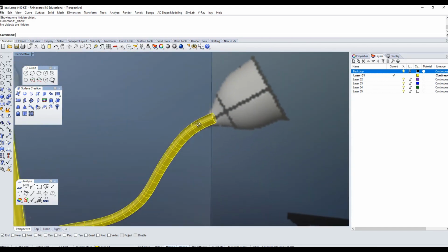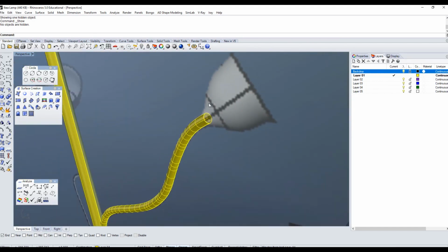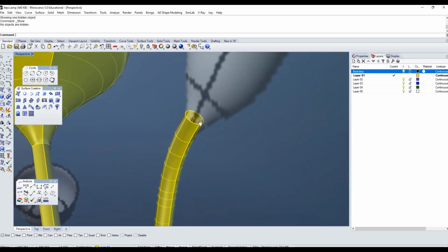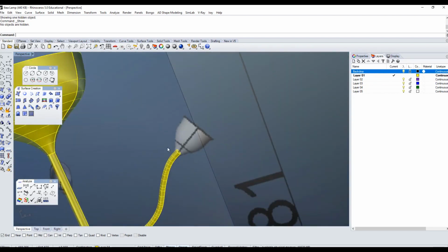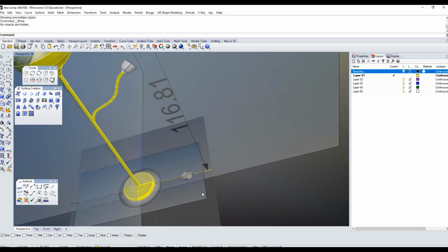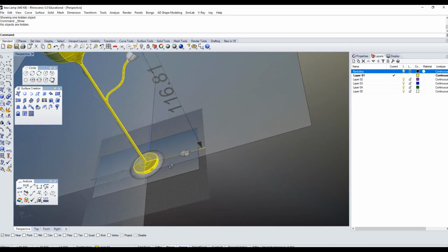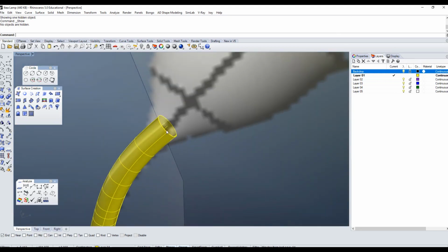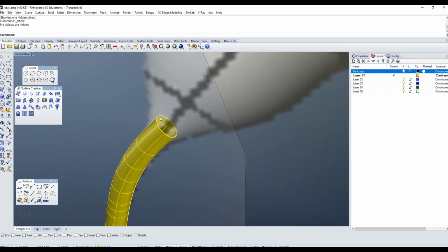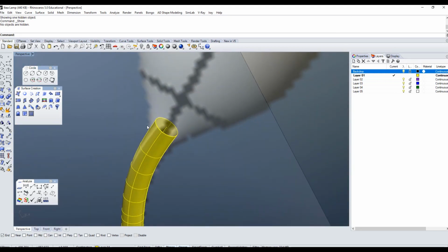So now I need to work on this shape, and this is interesting because I need to create an auxiliary construction plane. Okay, so if I press F7, actually my grid is already showing here. I don't need to press F7, but I need to reposition the construction grid along this.